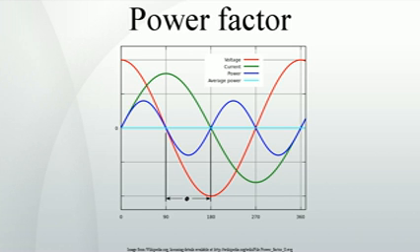Nonlinear loads. A nonlinear load on a power system is typically a rectifier, such as used in a power supply, or some kind of arc discharge device such as a fluorescent lamp, electric welding machine, or arc furnace. Because current in these systems is interrupted by a switching action, the current contains frequency components that are multiples of the power system frequency. Distortion power factor is a measure of how much the harmonic distortion of a load current decreases the average power transferred to the load.